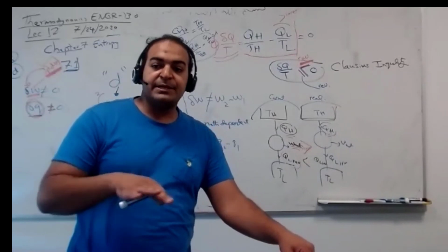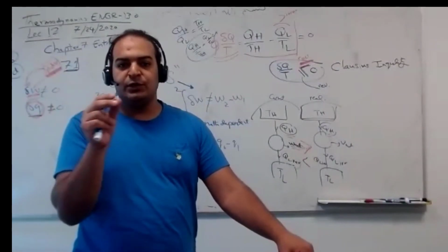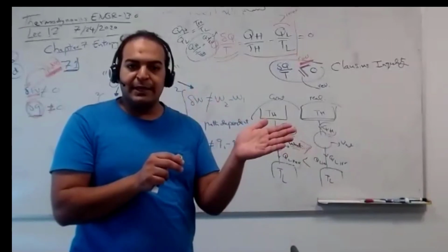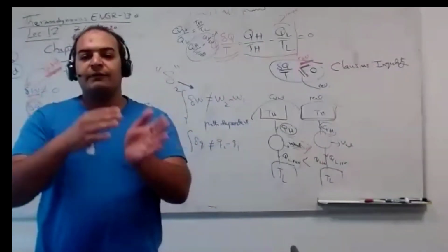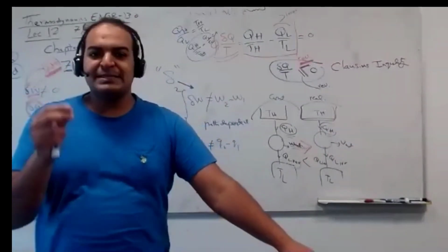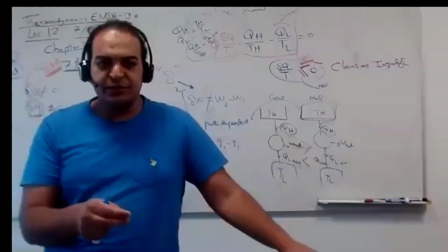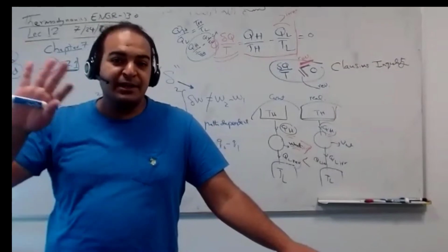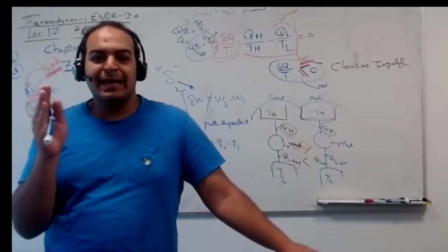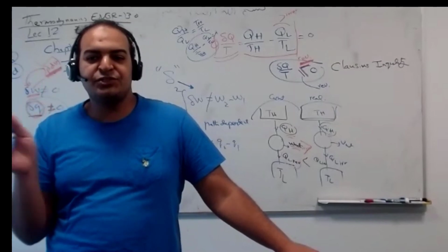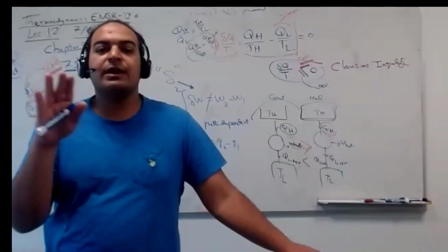Yes. The next three columns are called internal energy: UF, UFG, and UG. UF is internal energy at the liquid phase, UG at the vapor phase, and UFG is the difference. The next three are enthalpy. Enthalpy is U plus PV, internal energy plus flow work. The last three, guys, are entropy. Look at the last three: SF, SFG, SG. So whatever you did for U and H, V, you can repeat for S.